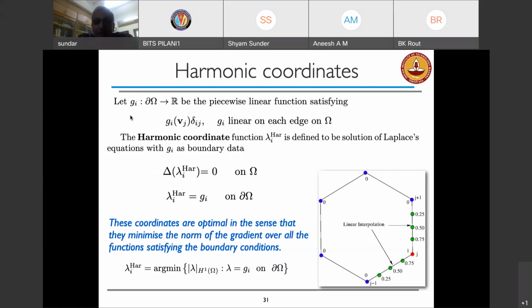So let's say that I would want to develop a six-sided element, right? And this element has to have shape functions. In this case, it will have six shape functions. The property of the shape function would be that if I'm writing the shape function for node j, it should be 1 here. It should be 0 on all other vertices and 0 on the vertices that do not connect to the vertex j.